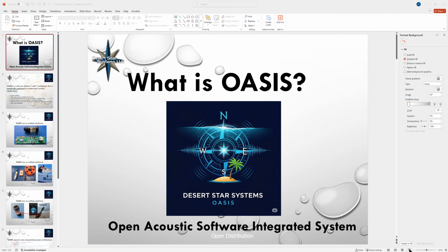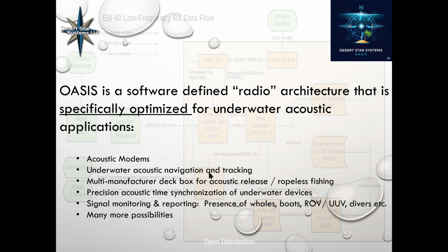So I'll do this slideshow here. As I already said, it's a software-defined radio architecture, however, one that's specifically optimized for underwater acoustic applications. They're quite different from radio applications. Frequencies are much lower in underwater acoustics, but you also need to be able to drive sonar transducers. They're very high impedance devices, and you have to develop several hundred or even thousands of volts. So it's optimized for that.